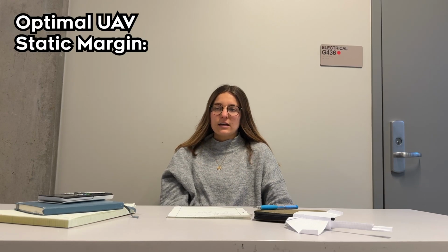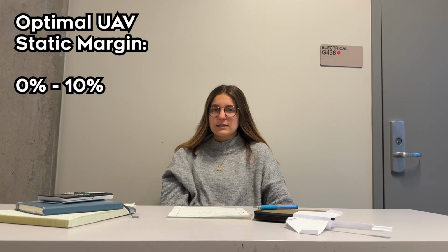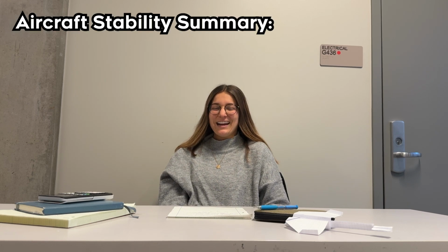Major differences between each of our models was the placement of the center of gravity. So for a UAV, we want our static margin to be between 0 and 10%. And so location of the center of gravity needs to be in a position that yields a static margin in that range. Our aircraft was stable, which is great.